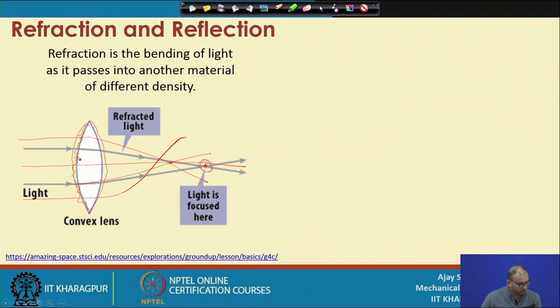That means, whatever things you want to transfer from here to here, instead of a circular point you will get an oval point, or some other shape. At that time you are losing many features of the light. That is why you require very high surface finish and shape accuracy on a lens.